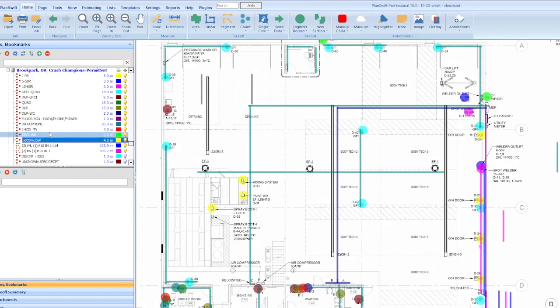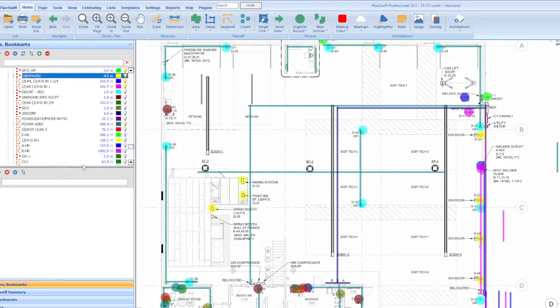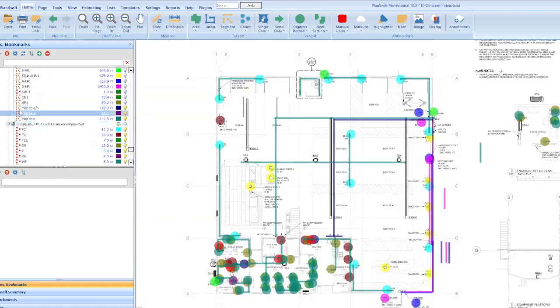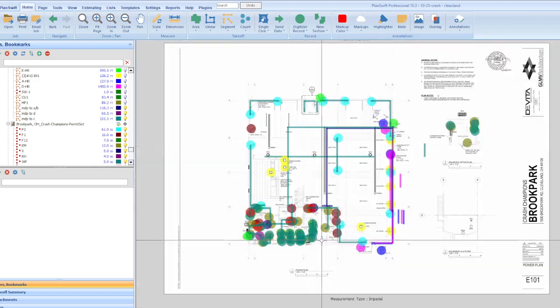So we had to, let's see. There we go. Oh, there already. Main distribution panel. Let me take it out. There we go. Main distribution to A and B is that one. Main distribution to D, take it out, is that one. Main distribution to C, take it out and put it back, is that one. So now I know those actual lengths, plus add like 10 feet.